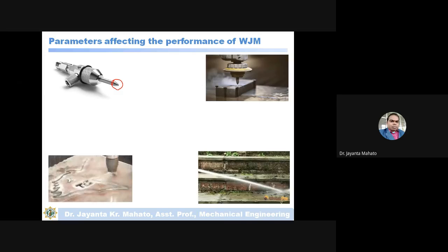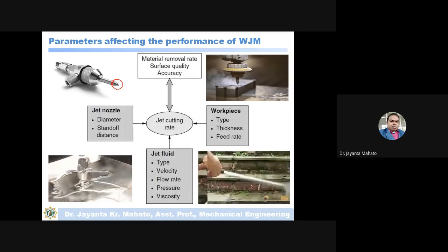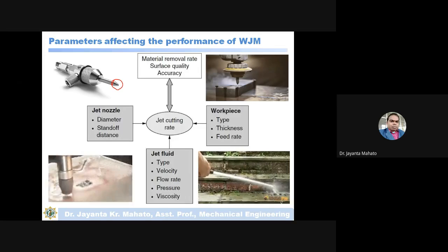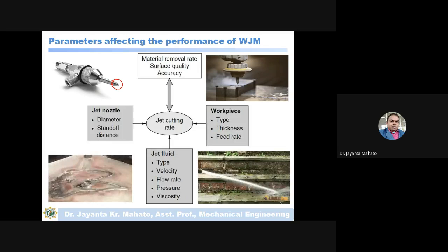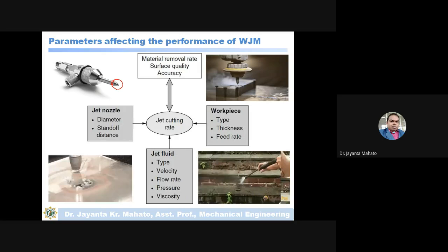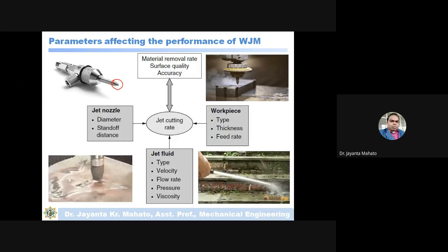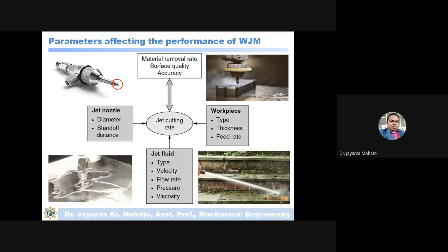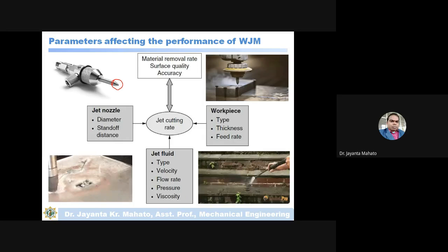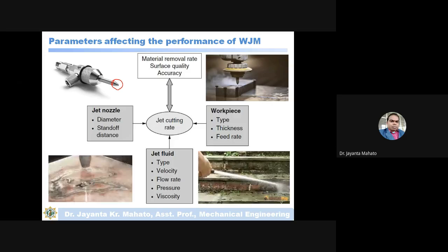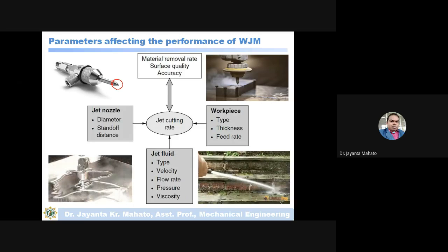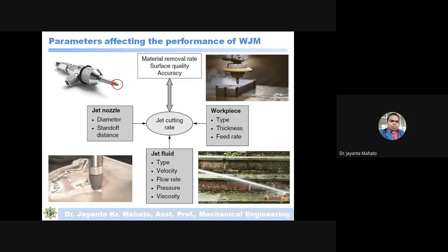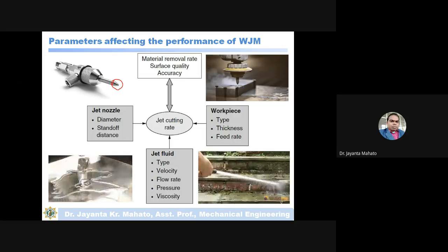Okay, so let us summarize the parameters. These are the parameters: the jet nozzle, meaning the diameter of the nozzle, and stand-off distance, meaning from what distance I am striking. So this is the distance between the workpiece and the nozzle.